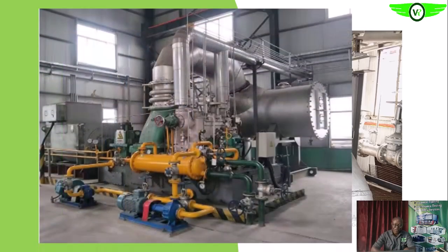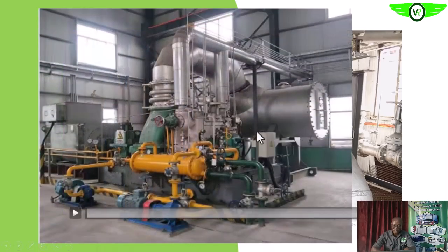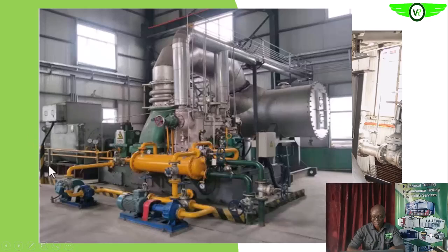Okay, all that we have been discussing so far, this is an example of it. The exhaust to your condenser. The vacuum is pulled from here. So this is the intake, and this is the exhaust to your condensers. Here we have the cooling water system, which helps to circulate cooling water. This steam turbine is actually meant to drive a generator, as you can see on the screen.